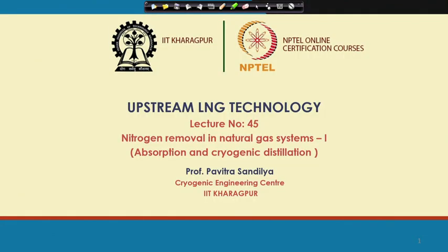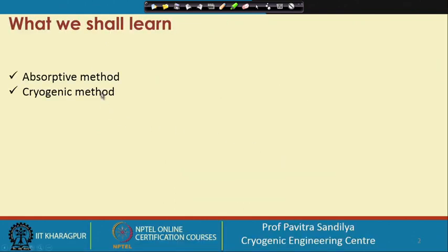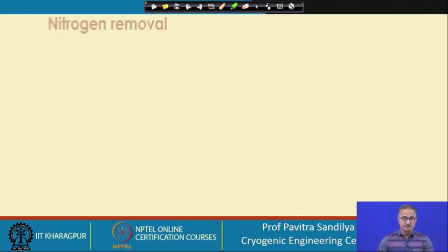Welcome. Today we shall learn something about the removal of nitrogen, and this nitrogen can be removed in various manners. In this particular lecture we shall be looking into absorption and the cryogenic distillation processes for the removal of nitrogen from natural gas. So, what we shall learn? The absorptive method and the cryogenic method for the removal of nitrogen.